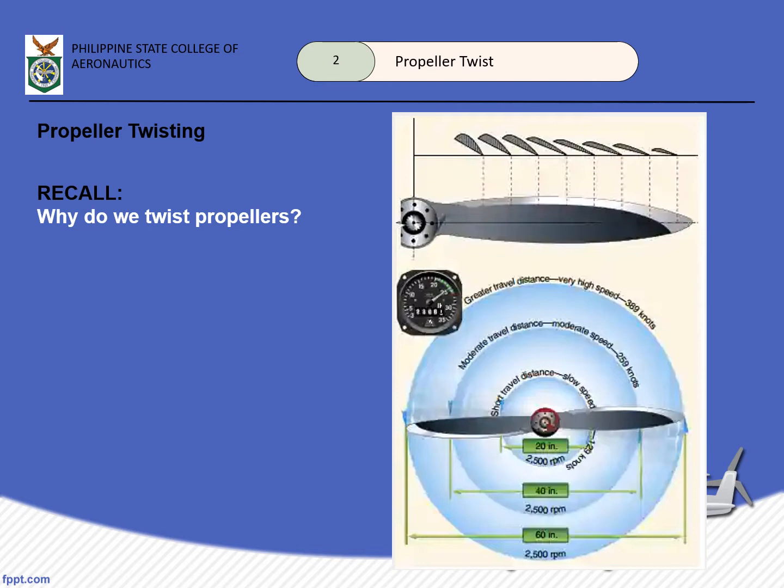So, that is where our stations come in, just like what we had discussed last time. And this is also where the question comes in, how does acceleration occur? The simple idea behind the acceleration is that the thrust should be more than the drag. So, it is done by engine power and propeller RPM. But this has a limitation, depending on what our power plant can produce, or our thrust available. And as we accelerate, there is an increase in drag.